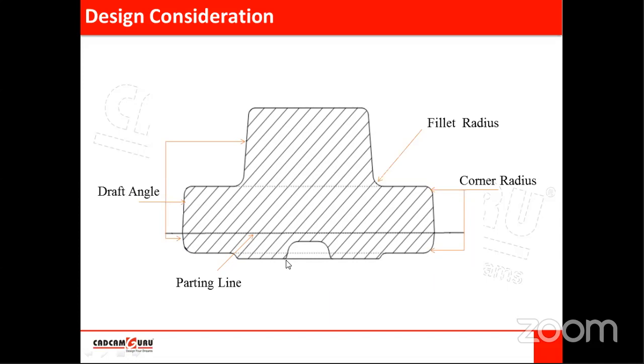But for holes or for cavities it will be exactly opposite. So here these faces are tapered in this direction, because it is a cavity, it is a hole. So it will be exactly opposite for cavities.